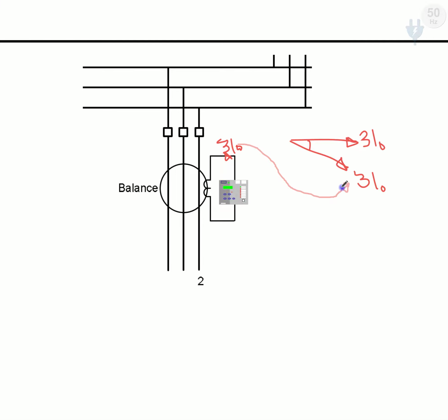Why does this deviation in the angle occur? This is because, when the 3 phases go inside the core balance transformer, we have some air gaps. So due to these air gaps in the core balance transformer, we will have some deviation angle of the measured zero sequence current.